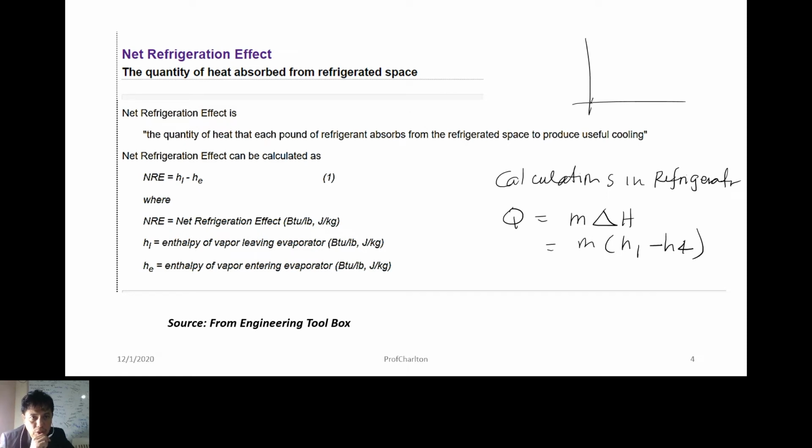Lagay ko rito, no? So we have this diagram. So this is 1, superheated at the end of the compressor. 2, 3 is the discharge of the condenser and entrance of the expansion valve. The expansion valve expands the refrigerant gas and it lowers the pressure at constant enthalpy.